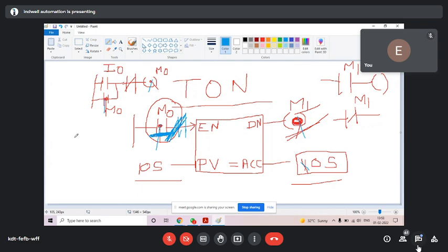This is the software part. If you want to stop or reset it manually, you will have one manual switch connected to the PLC, correct? Suppose that switch is I1. So you can put I1 here. Manually you will have to press I1. As you press the I1 switch, it will break this latch and its enable will be broken. It will be reset. But if you want to make it an automatic reset, you have an automatic address, a flag. This flag will break it automatically. You don't need to press anything. Okay.